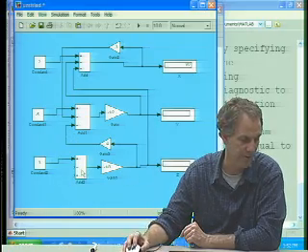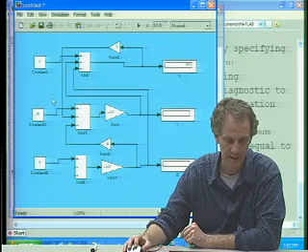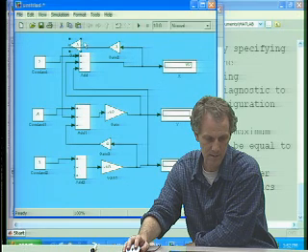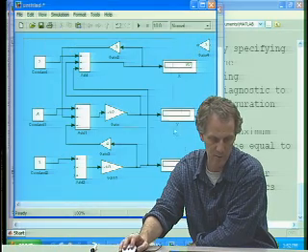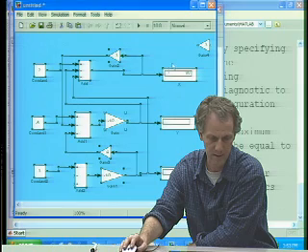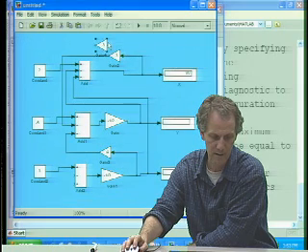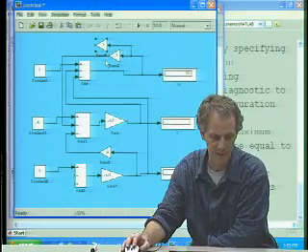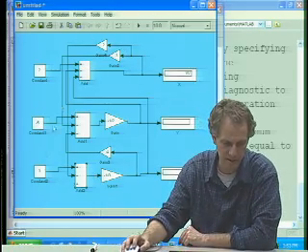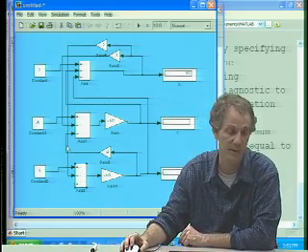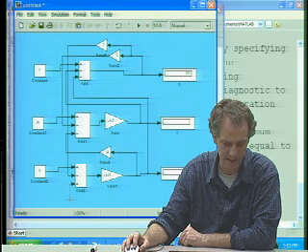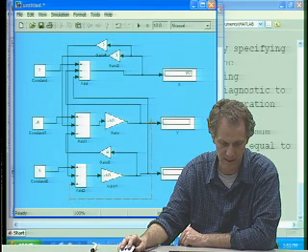To fill in these last two holes, I need a negative 2x. And I can do that with a gain up here. I'm running out of room, so you can actually grab a whole bunch of things at once and then drag the whole thing to give yourself more room. All right, so I drag that back, change the gain so it's a 2, and then control click. It wires it all the way down to the second spot in the third equation. And then finally I have a plus y, so I could actually just drag this arrow back. I don't need a gain. Just got to get all the way back to the y location.